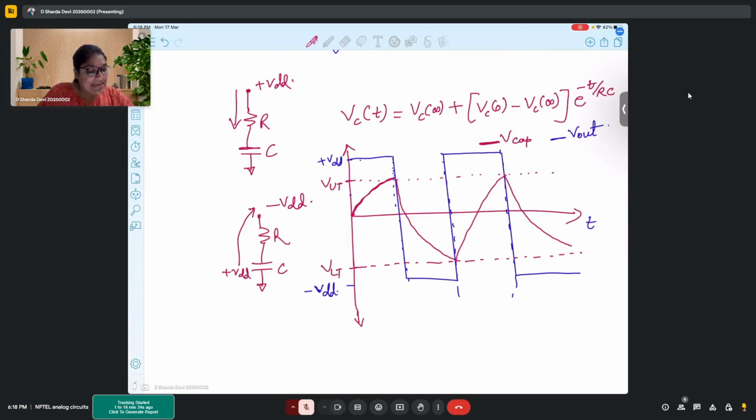What I said is that with this triangular wave, you can tweak the time constants in a way that it looks a little more accurate to an exact triangular wave. More or less, this is a little curved one, right? But you can tweak the RC value such that it looks like a cleaner triangular wave. That is what I said. But basically, the idea is that you can get two types of waves, one is a square wave and one is similar to a triangular wave, from the same circuit. That is the idea. Okay?